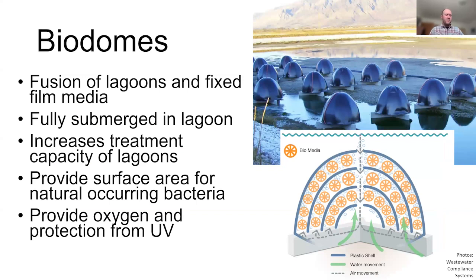Okay, then the last thing I'm going to talk about really quick is just these biodomes, and I'm going to pass over to AJ, because these are a fusion of lagoons and these fixed film media. So these are submerged in the lagoons, and they utilize these domes with a bunch of surface area, and this bacteria attaches onto these biofilms, and they add oxygen into there, and they treat water as it's in between all these different layers. And they also protect the bacteria from harmful UV. That's a concern for them.